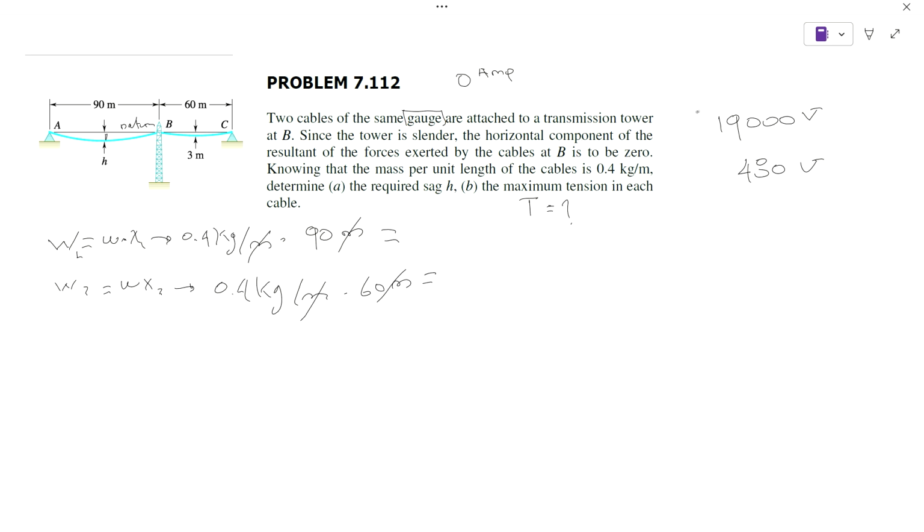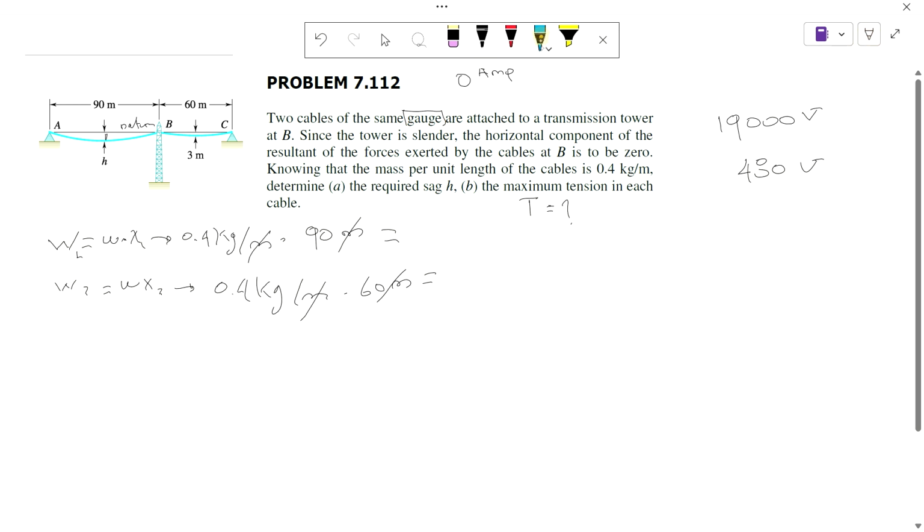The second thing is we're going to do a free body diagram of the cable. Remember that we choose the bottom point where the tension is a component completely horizontal, and that looks like so. So this is the cable, exaggerating the curvature. We're going to choose a point right here. Let's call that point P, and we have another point right here, which is my point B.